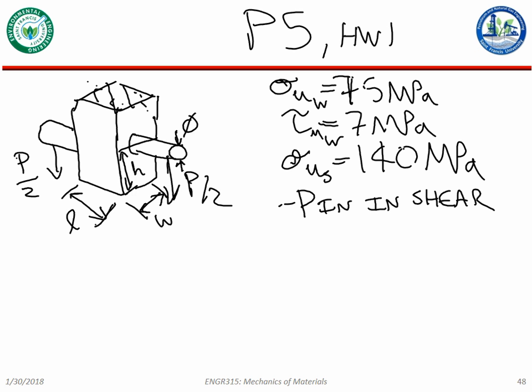The block, though, is kind of a mix of everything, right? I can cut different cross sections and get different things. You could make a cross section through the pin that goes this way, I guess. But would that have more or less stress on it than the cross section we're already looking at, one that's vertical? Why would this cross section be of more interest than this one?